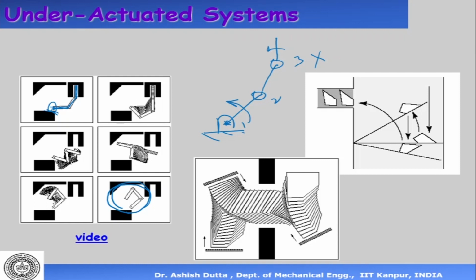Okay, if I start swinging this, what will happen is theta, it will have angular velocity, angular acceleration. Okay, so this angular velocity, angular acceleration will travel in the forward direction. So although there is no actuator, link 3 does not have an actuator, it will still have some angular velocity and acceleration because of the acceleration coming from the previous link. Okay, so by moving the previous joint, I can still make this fellow go from this side to this side. Okay, these are called under-actuated systems.